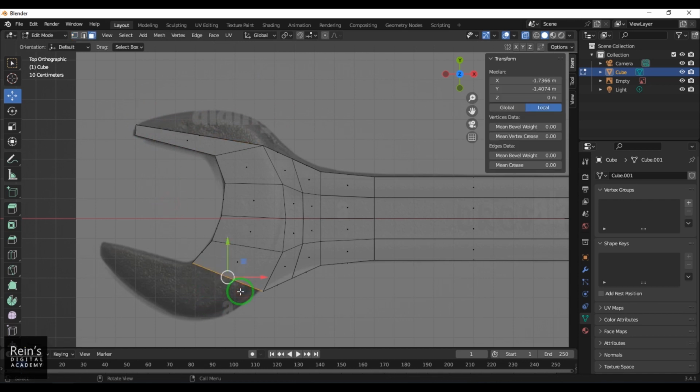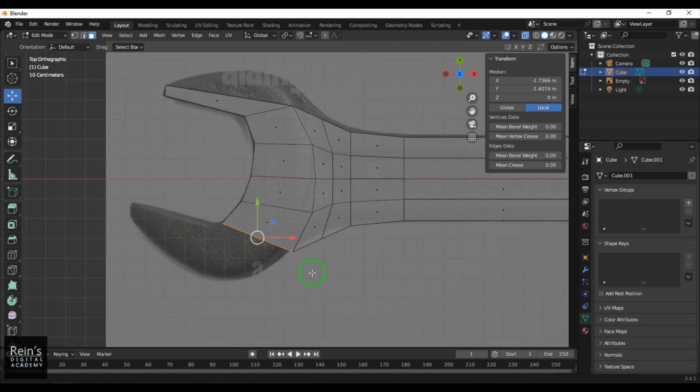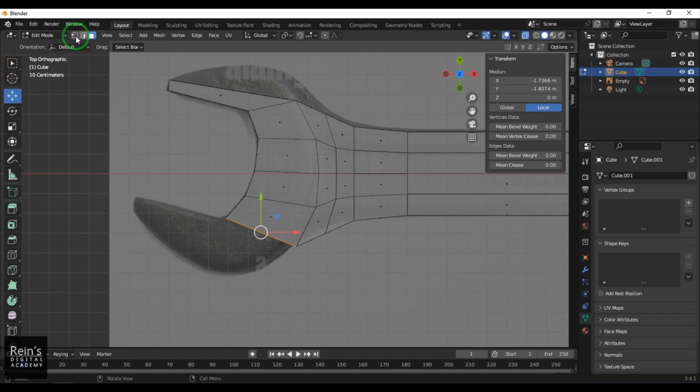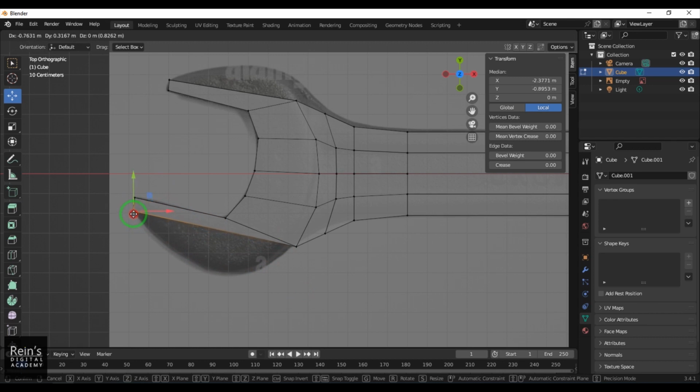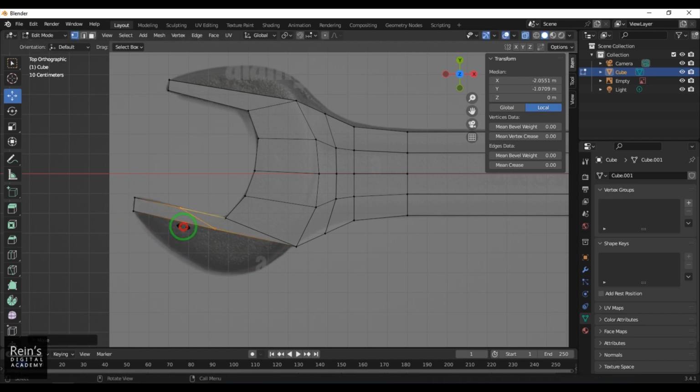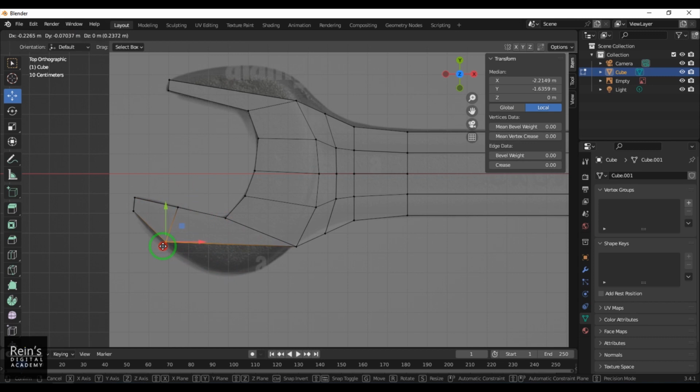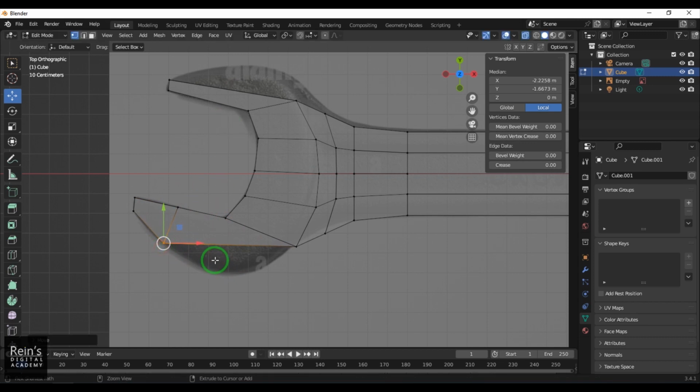So what generally that does is I'm able to switch between vertex 1, edge 2, face 3. So I select the face mode, press E to extrude, 1 for the vertex mode, move it there, move it there. Again Control R for the split tool and then select the vertex and then match those points. Control R and then move it.